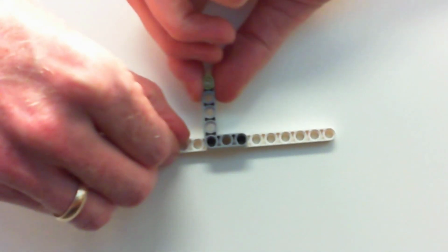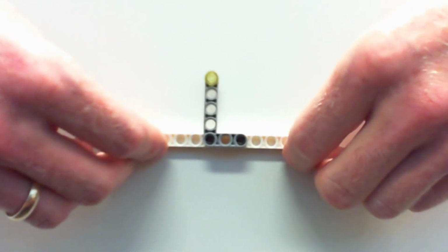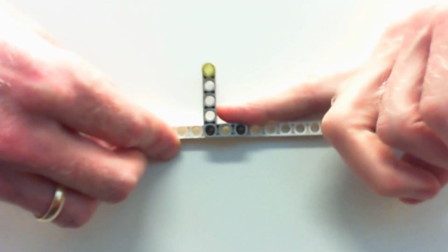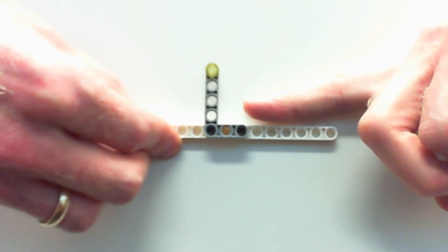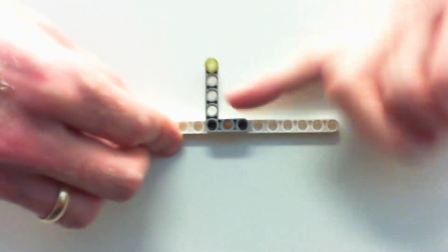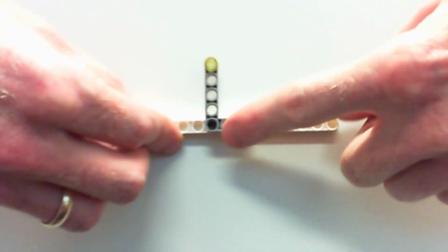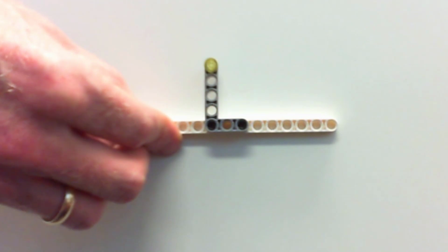I can't pull on this, I also can't push on this, and so it has both resistance to a force this direction as well as a force this direction or this direction. Okay, so two forces, and we're assuming here that they're still orthogonal. I could assume one's horizontal and one's vertical, probably computationally the easiest given the system. And then additionally a couple around the middle there. So that is a fixed support providing three reactions.